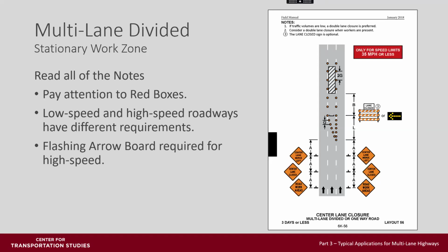Also note drivers are being directed to merge to the left. It's important to give drivers a single direction. Use of a double arrow in this case often results in driver confusion, and experience has shown crashes result, including drivers hitting the arrow board.